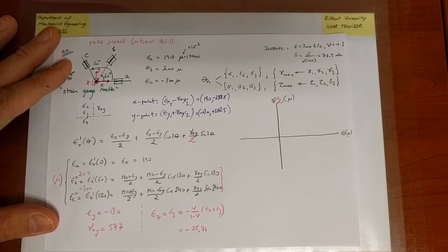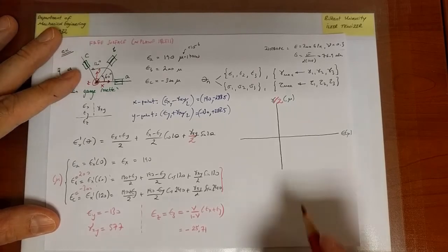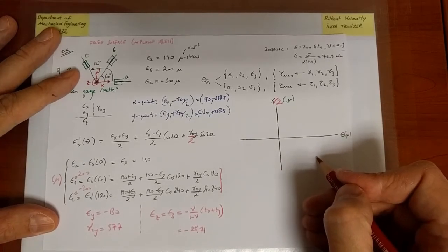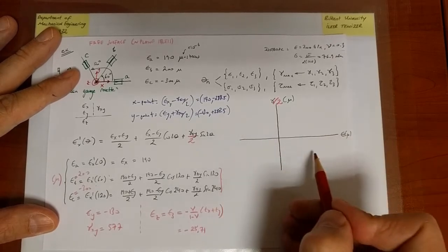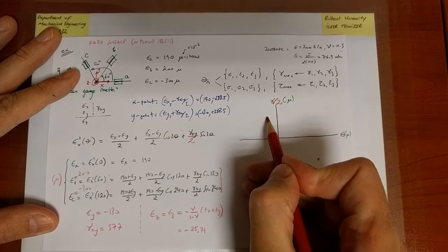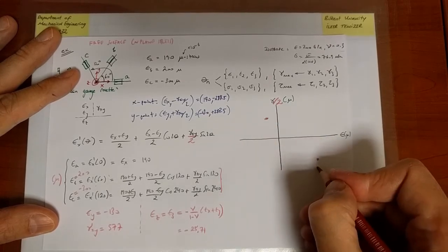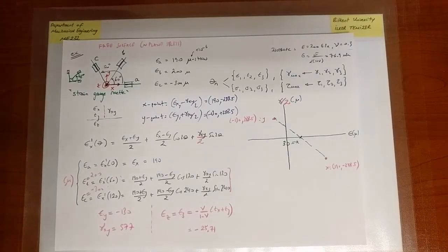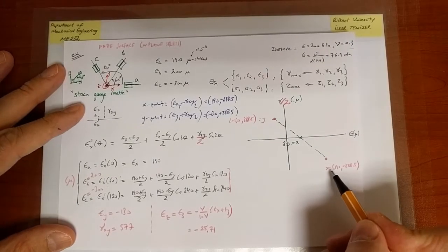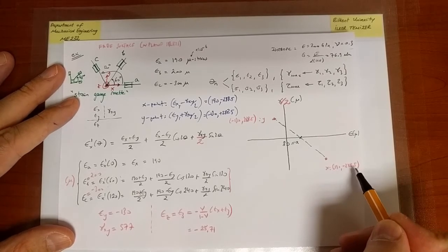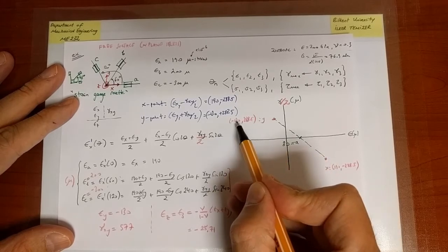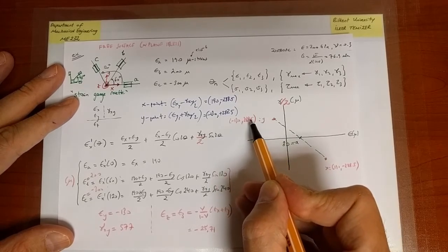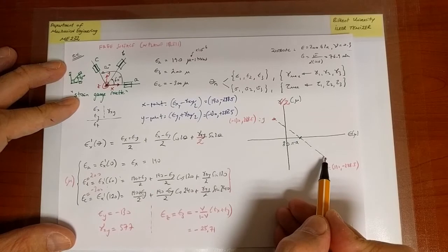So then I go ahead and put those points on my map. So perhaps not to very good scale, but one of these points, let's say, goes there. The other point goes over here, okay? So this is the x point. Let me continue after a tiny glitch. I was plotting the x point, which is 190, minus 288.5, and I plotted here as well the y point, minus 130, 288.5, and then we go ahead and draw the diameter.